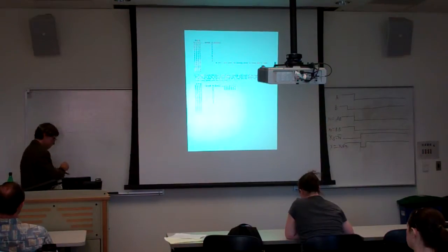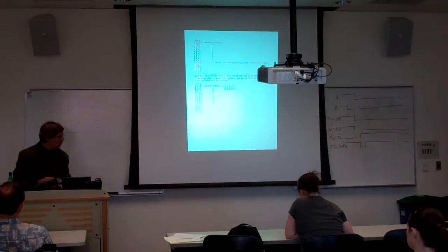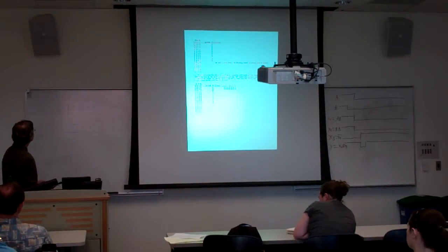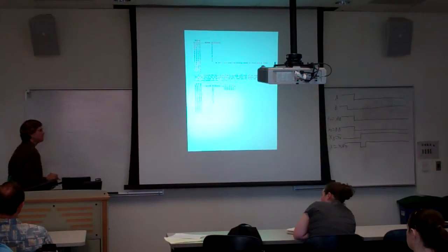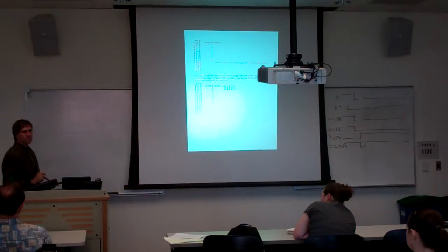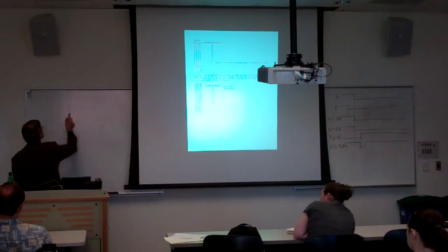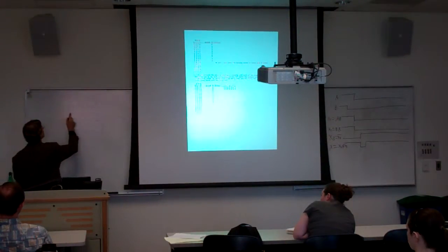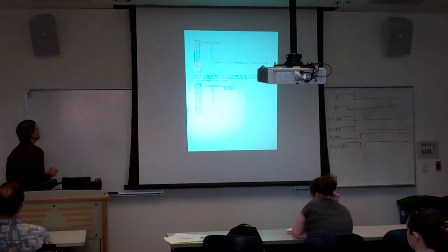I think that might have been one of the segments. So something like this, you need to cover the ones, that's all you're required to do. And it kind of helps maybe to start off with the outliers. So this one here kind of looks like it's by itself. It's only got a 1 next to it, and it's got some don't cares below it. And if you include this, you can cover both of those ones at one shot. So you want to try to cover both of those. You've got some don't cares down here. And if you go ahead and throw those in, you'll get a bigger rectangle, smaller number of gates that you need to use.